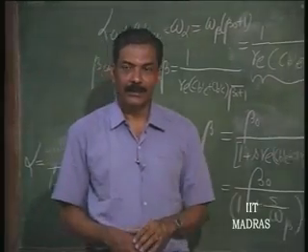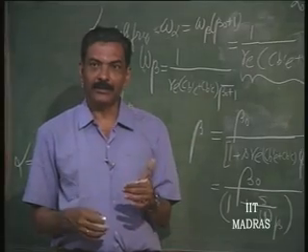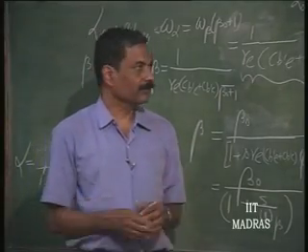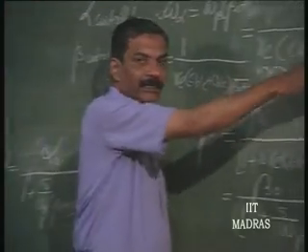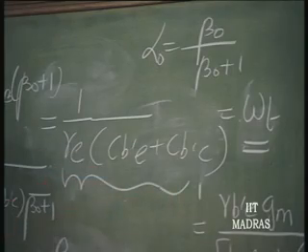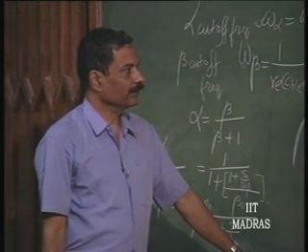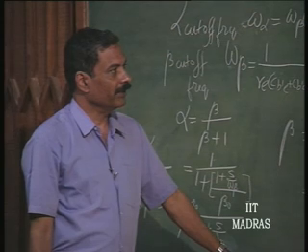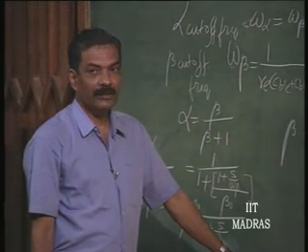This is the same thing, even in the case of a FET it is GM of the FET divided by C total. Okay. So, instead of CB dash E plus CB dash C, there you will use CGS plus CGD. So, this parameter is quite often used in evaluating the high frequency performance of all the wideband amplifiers.